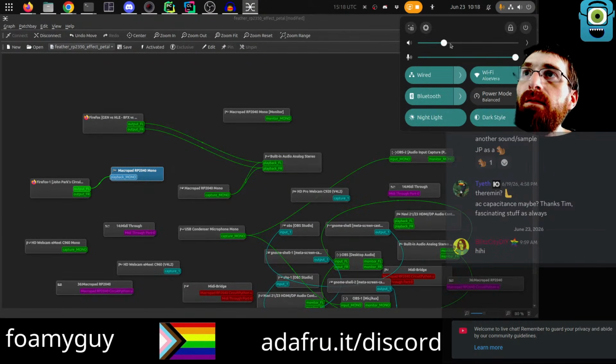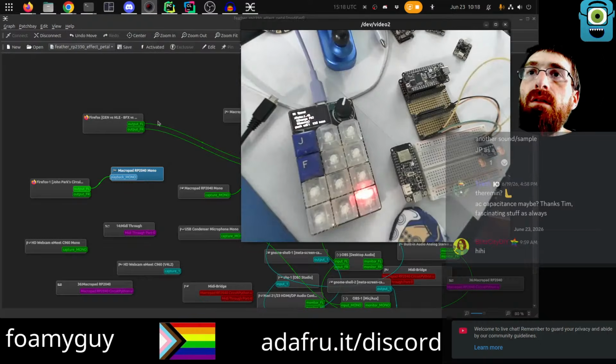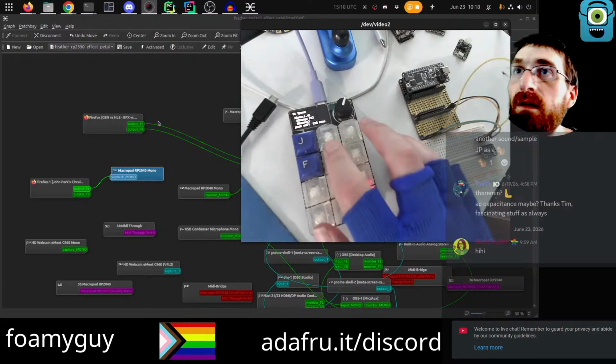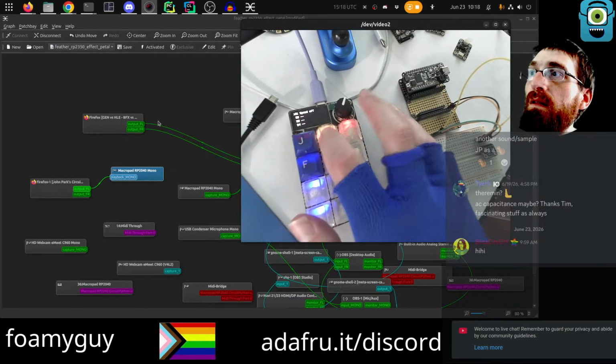Well, I'll tell you. In CircuitPython, I'm importing the Adafruit character LCD library. I'm setting up a 16-column and 2-row display here over I2C. And then I am creating a little message here, which is this.